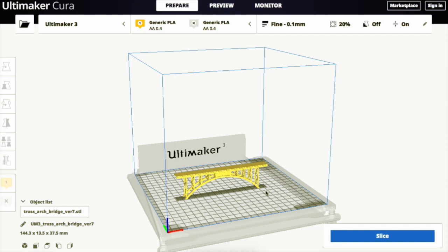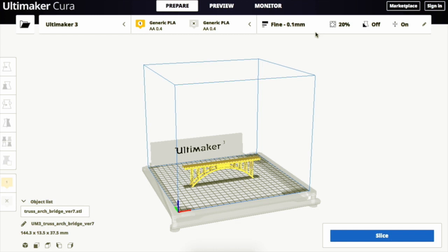An important number to keep in mind when considering whether or not to include support structures in your 3D print is 60. The general rule is that if your project has an overhang or extending features that is at an angle of 60 degrees or greater, you need to have support structures to ensure a successful print. The letter Y is a useful letter to visualize this concept, as the angles of the two lines are just enough that no support structure is needed. Any angle larger than this will need a support structure. In our bridge model here, we have several areas with overhangs greater than 60 degrees, so we definitely need support.